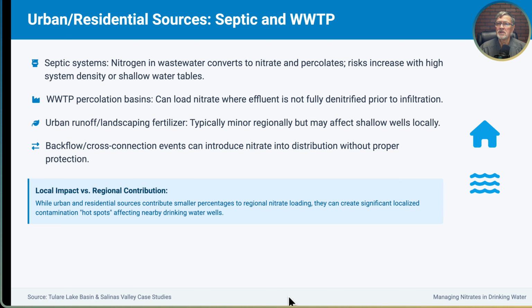That's probably something that needs to be done. It's an impact study that needs to be done, and you need to make sure you've got proper separation and proper design so you're not doing excess loading of nitrogen to the groundwater table, and that's especially important when you have shallow groundwater tables. So those cumulative impact studies are very important. We should really see those in other areas too. California uses those. I've started seeing them elsewhere as well, and that's going to really inform you in how you're going to design these leach fields and systems to minimize nitrate loading to groundwater.